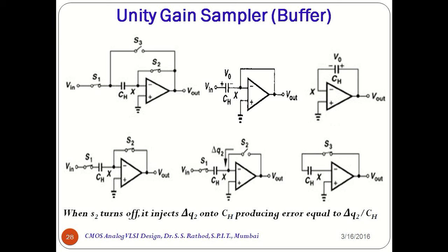For example, if S2 is realized by an NMOS switch whose gate voltage is equal to VCK, then delta Q2 will obviously be equal to WLC0X (VCK minus VTH minus Vx). Although the body effect makes VTH a function of Vx, delta Q2 is relatively constant because Vx is quite independent of the input voltage. The constant magnitude of delta Q means that channel charge of S2 introduces only an offset rather than gain error or non-linearity in the input-output characteristics.